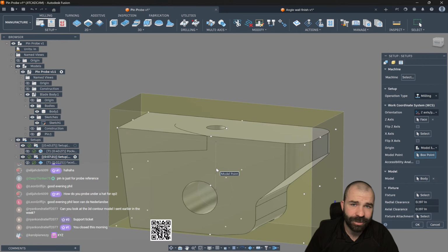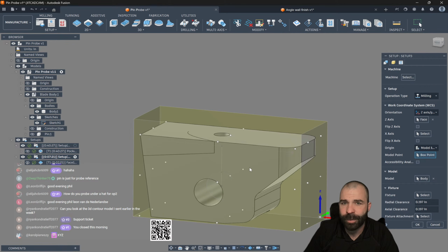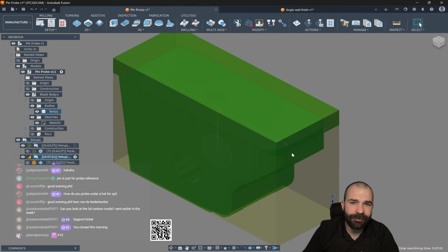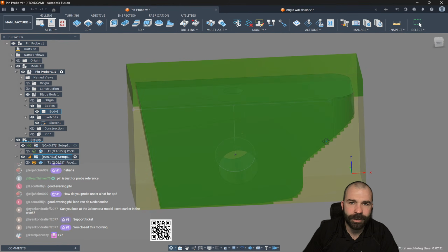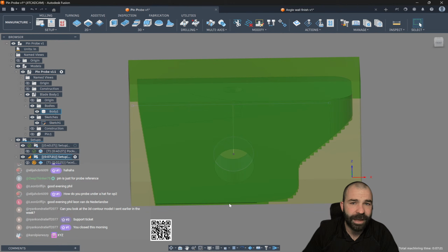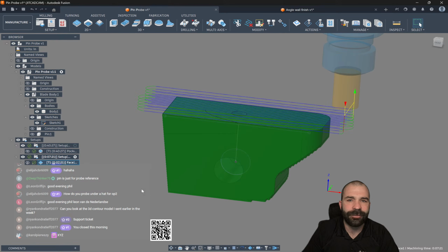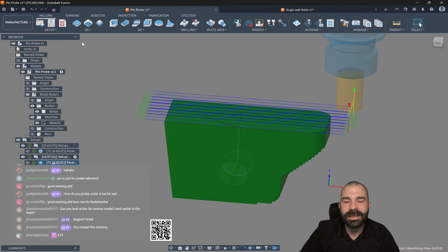That's what would work very well. Again, guys, I know a lot of you out there looking, why wouldn't you machine it from the side? Because we're demonstrating taking the hat off the part and also utilizing something like WCS probing. So with that, again, I may have my machine stop here to hold that part. I'm going off the bottom, which should be flat because we should have machined the other side a lot more than I did. But the whole goal here is once I now deck off the hat, I can then follow this up with my WCS probing or whatever you want to do at the end of the day.